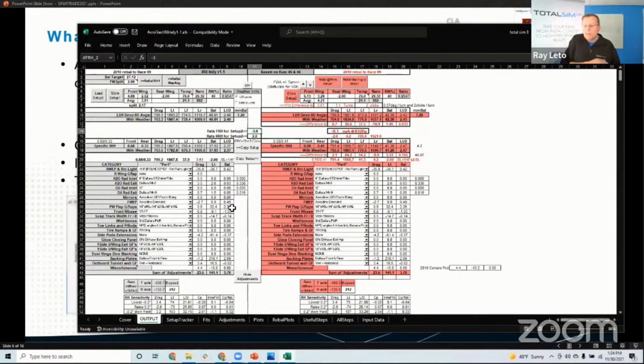And this is what happens at the top end of motorsports all the time. You're watching the telemetry, you're seeing that the aero balance is a little bit off. Okay, we need a half a turn of front wing. How do they know that? That's because they mapped this out and they understand that to do X% of aero balance, it's this much front wing to do that. They're not guessing. This stuff happens because we've got this data.